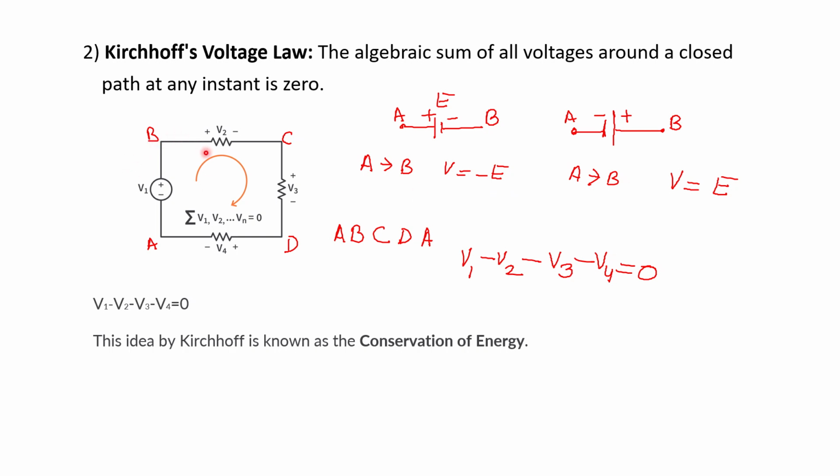And if you see the circuit element resistor, current always flows from higher potential to lower potential, and if we see a current direction, then one terminal is positive and the other terminal is negative. So for applying KVL, you have to assume the polarity of the circuit element, then we will apply Kirchhoff's voltage law, and it is very easy to write the KVL equation.